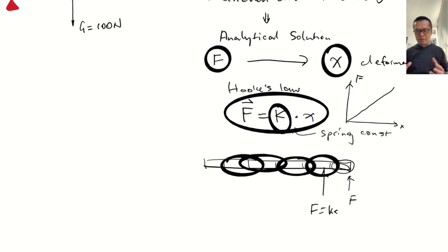And finite element analysis is basically an exercise to establish a complex relationship between your loading, the force and the deformation in a real material, such that I can understand, okay, if a car goes past the bridge, is the bridge going to permanently deform or just slightly deform within some tolerance? This is a very important design question to ask in real engineering. Now, what we typically have is this value of k.